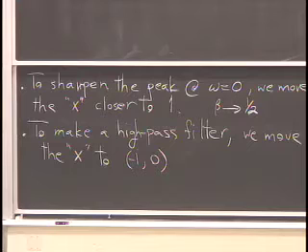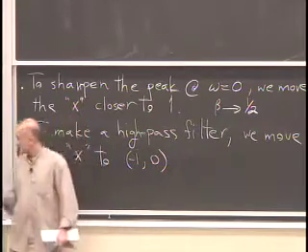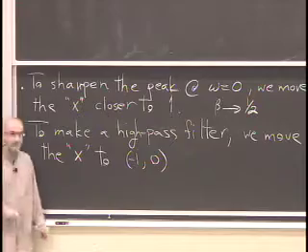If we want a sharp high-pass filter, we move it closer and closer to -1. So you've got this knob. And all you're doing is grabbing a piece off the shelf, something that's already gone into production. You've got 1,000,000 of these. And the only thing you've got to add is a storage element and a scalar amplifier. And you put it in this configuration, you've built your new filter. You may even have a box with a knob that adjusts this beta.